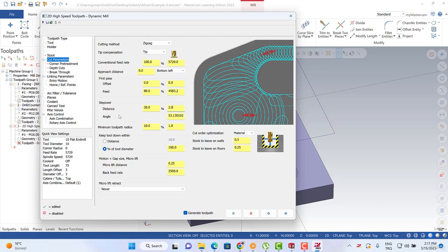This is the cutting angle. We're going to use that angle for our cutting process. According to my tool diameter and my step over, that can be calculated easily. You can also write this one, and my step over and tool diameter percentage are also calculated here. You can choose this one, for example, so you don't need to care about which tool diameter you should use. You just focus on the cutting coverage degree here.